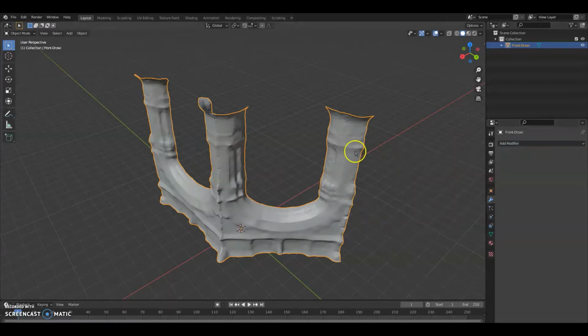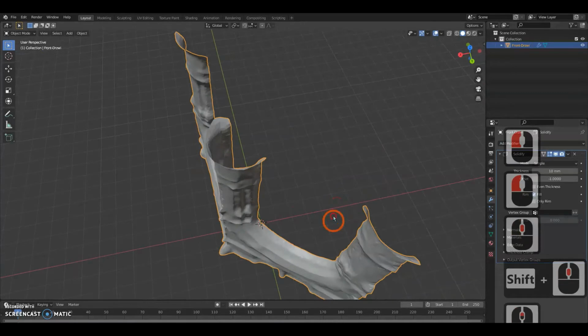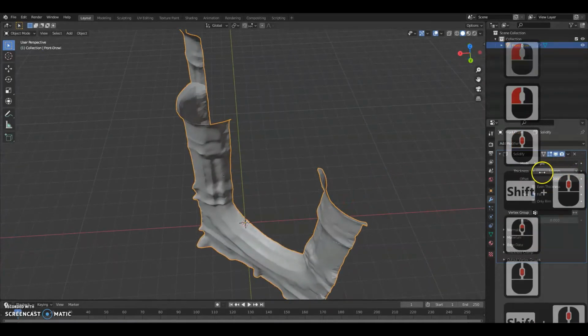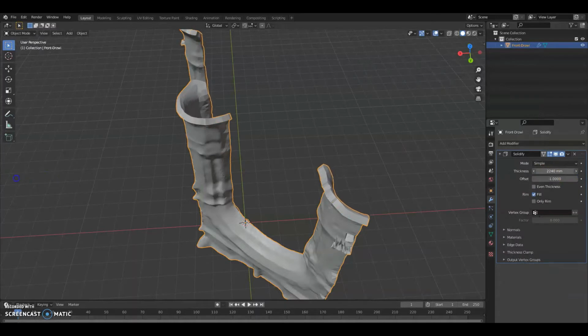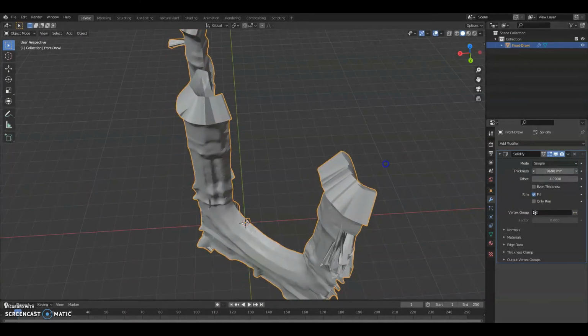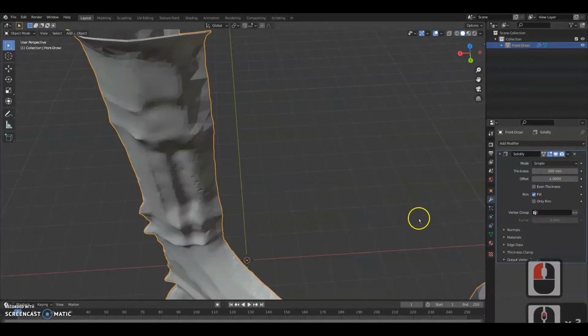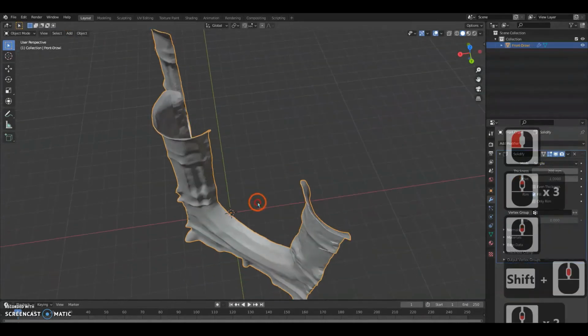So what you want here is, again, you want this selected, go to add modifier, solidify. And then you can see if you grab your thickness bar, you can drag it and it'll give your object different thicknesses. Right? So negative will be forward, positively backward. So 2 millimeters is going to be a little bit thin here. As you can see, we're at 200 millimeters, and it's honestly probably what you want here.